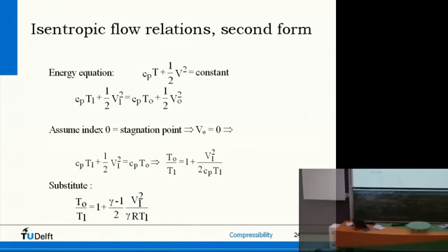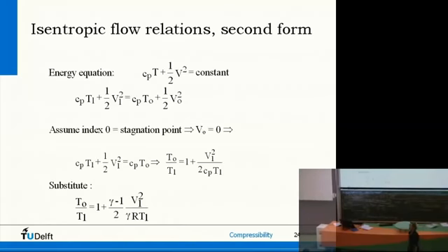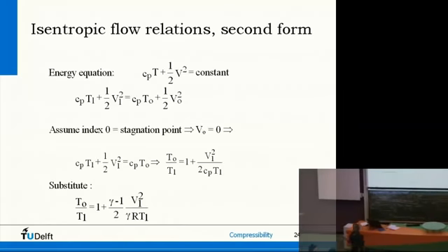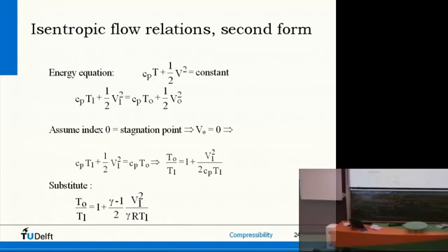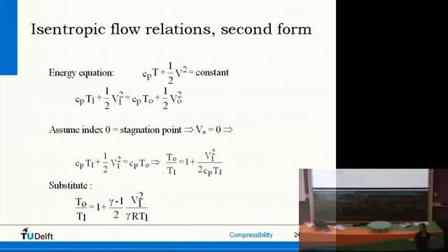Okay. So, what are we going to do? We're going to derive... we have the compressible flow equations. We are actually fine. Energy equation relating temperatures and speeds, isentropic flow relations relating density ratios to pressure ratios and temperature ratios. But sometimes it's easier to work with things like the Mach number. So you can recombine these equations into a different form. They're not more information, just in a different form, which might be handy if you have information about Mach numbers.